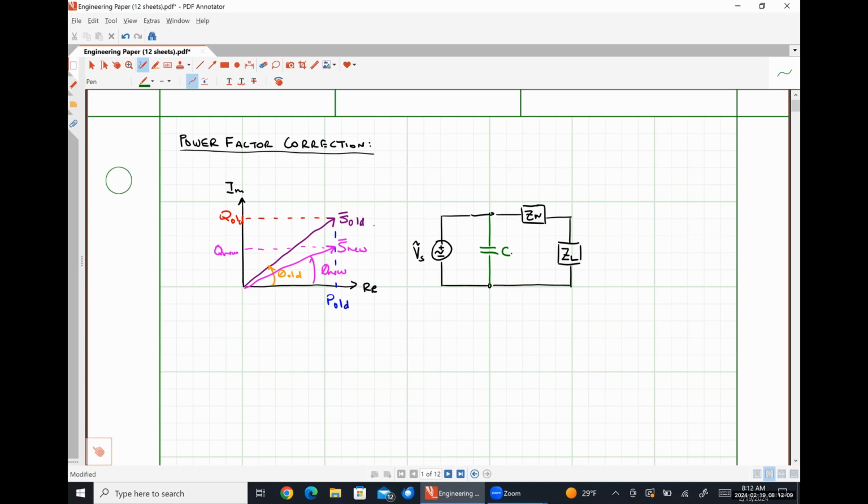However, our transmission line is also typically going to be an inductive load. It's going to be significantly smaller than our actual load. But putting our capacitance in parallel with the voltage source corrects for both the transmission line characteristics and the load characteristics. So this is typically where it'll be done. All right, so we have an idea of what we're doing. Now let's go through some math.